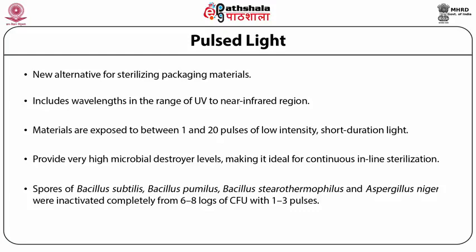Light pulses apparently do not affect the nutrient retention in food, but a detailed study is to be done. Pulsed light treatment costs are very encouraging. Packaging materials compatible with this process will transmit light over the broad spectrum employed. LLDPE, LDPE, nylon, EVOH, HDPE, and PP have all been used. Package geometry should not allow any shadowing on the product, or the light exposure may not be sufficient.